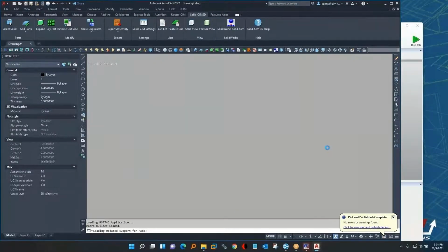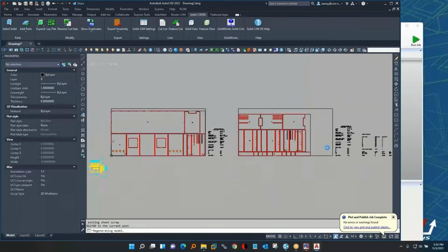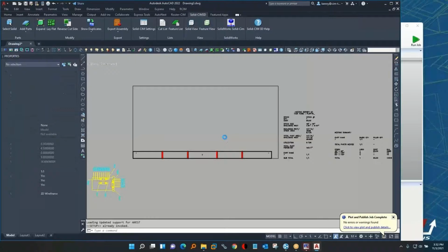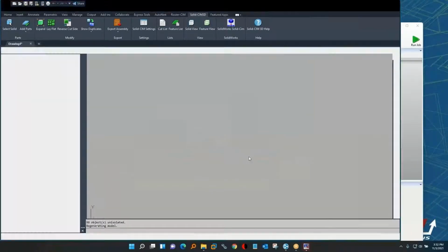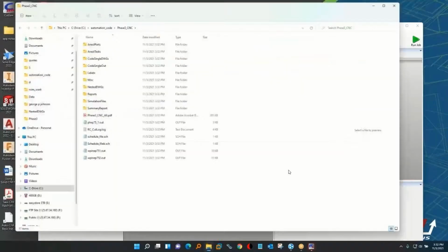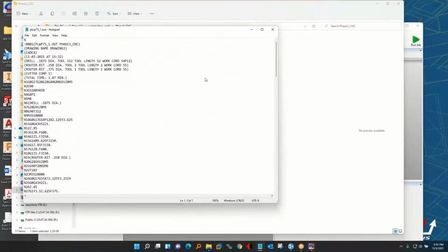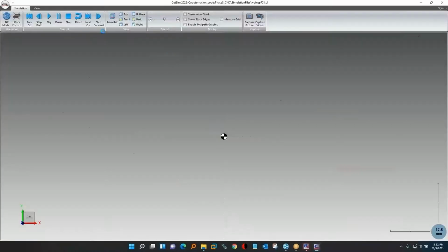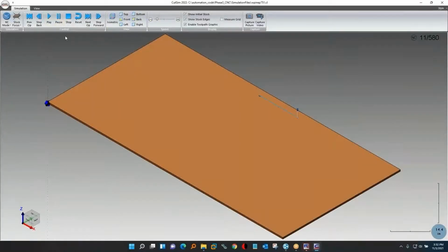I think there were two materials left that needed machining. So here's our first material, and it optimized the yield for these parts. And then there's the second material where it just had one little piece on there. So now from that 3D assembly, we've made a program to cut the parts on the saw, and we made a program to cut the parts on the router. We've got labels for everything. We've got the NC code files that are ready to run. We've got toolpath simulations.